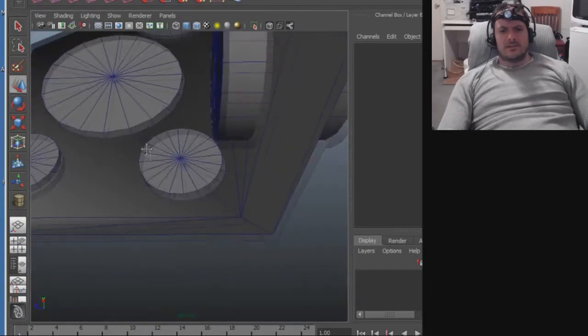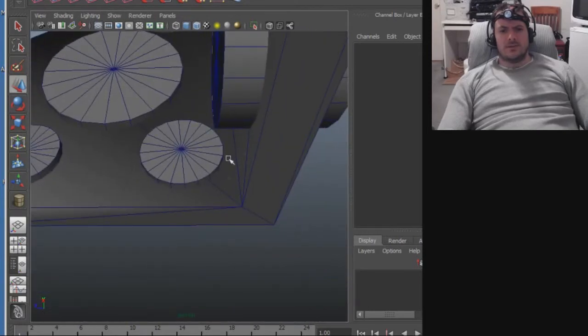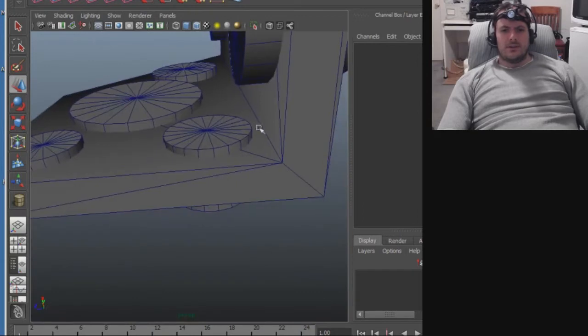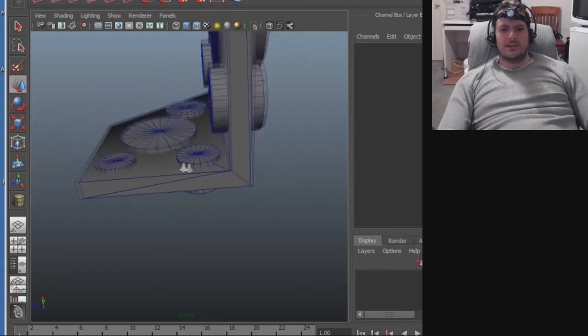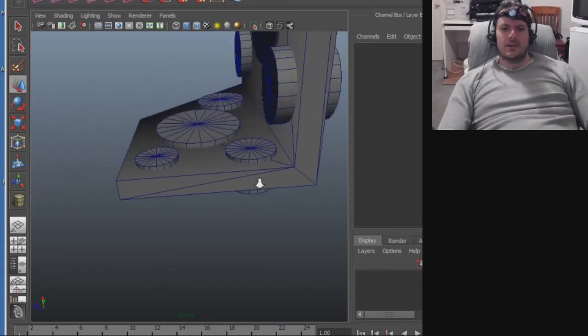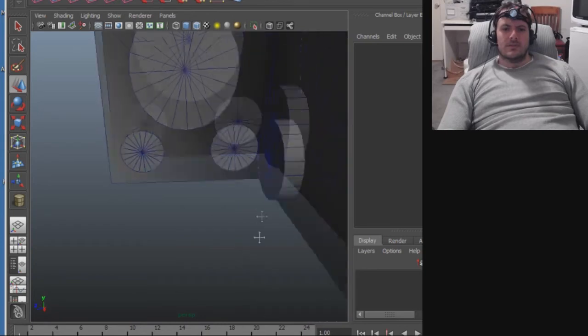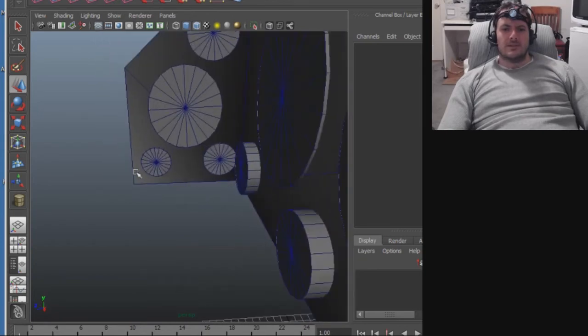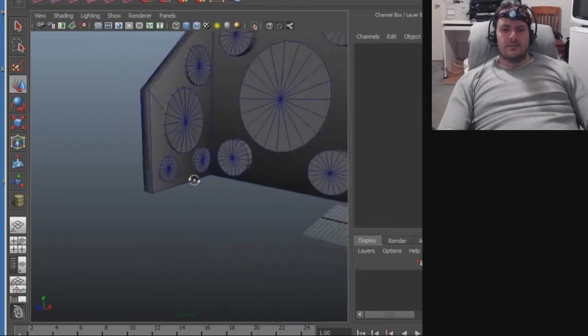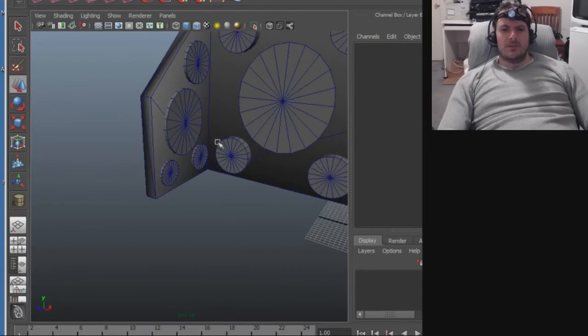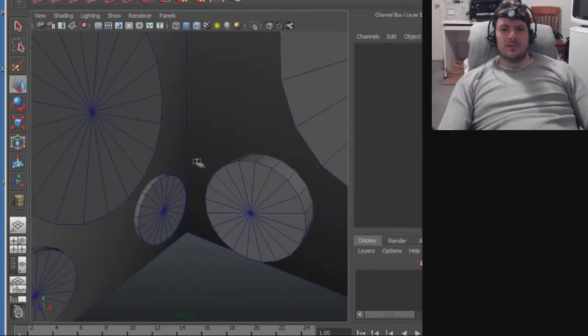I'm assessing this corner here. It is pretty close to the edge right here. But I think that the strength of this wall will carry over into this so that it doesn't actually matter how close that is to the edge. So that's a non-issue. But this does matter. But this is still like one pillar. Even though it makes a 90-degree turn, it's still one solid pillar. So it's okay if that's close to the edge.